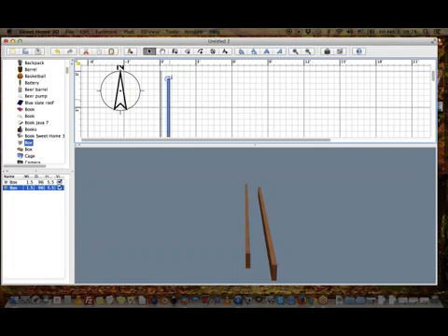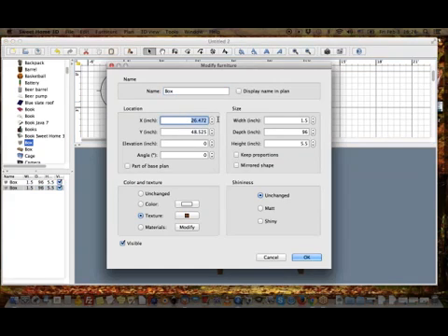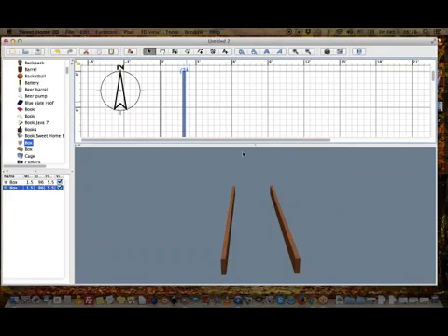Okay, so now I have my board here, and what I'm going to do is I'm just going to copy and paste a copy of this because I need another stud on this module. And I know that the spacing between studs on my wall modules is 24 inches. Okay, so now I could go here and tell it to go to X24, and here I maintain the 48, right?